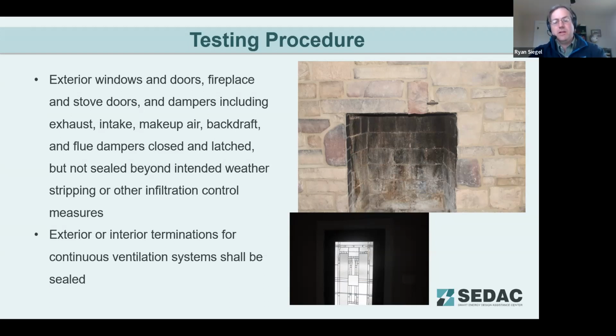One area that we do see this is for roof relief openings, is making sure that that cover is able to be removed. A tarp or other piece of material can be fitted across it, and then the cap can be reinstalled over it, so that way it holds that material in place, and also the cap doesn't go flying during the testing.